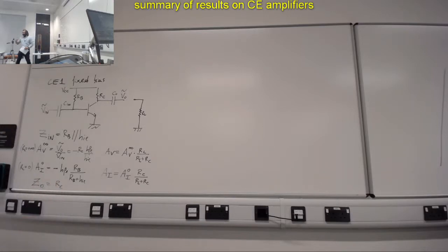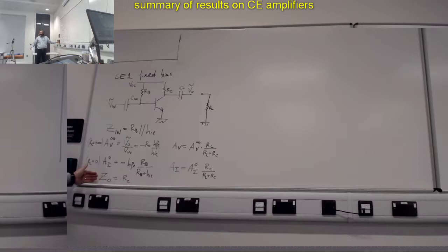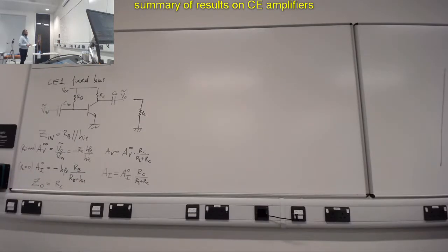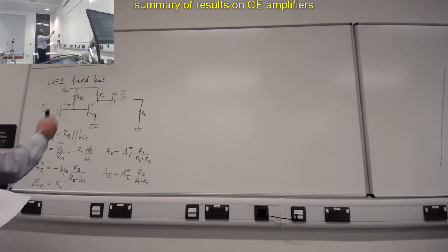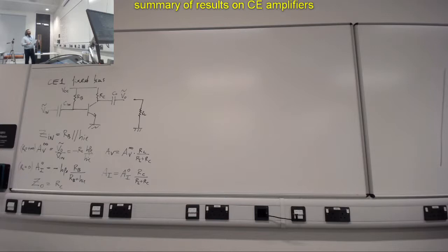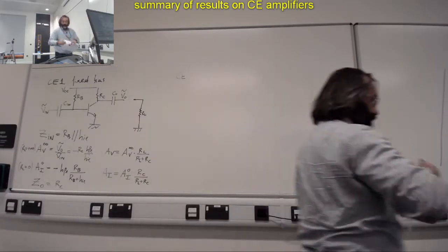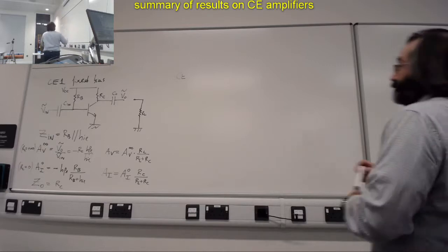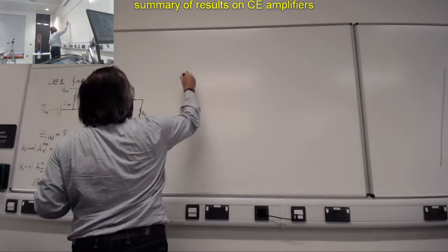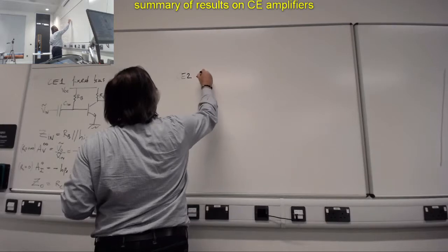So in general, for any amplifier, we are after these 4 parameters: input impedance, voltage amplification, current amplification, output impedance. And last week we also said, okay, if the C2, how was C2? This was with emitter bias.